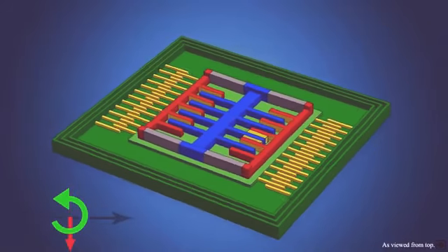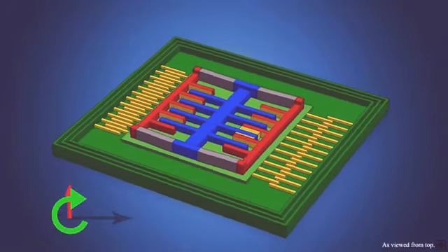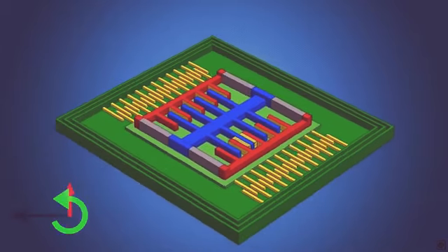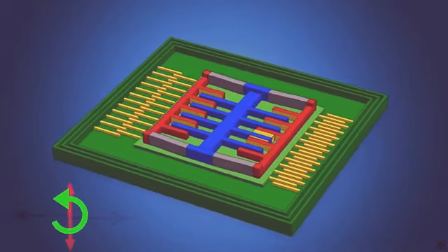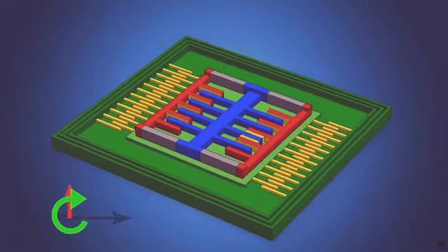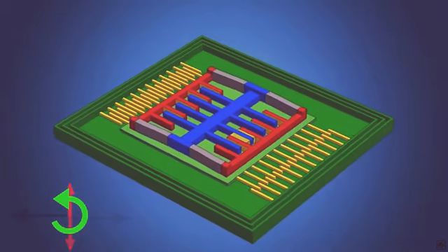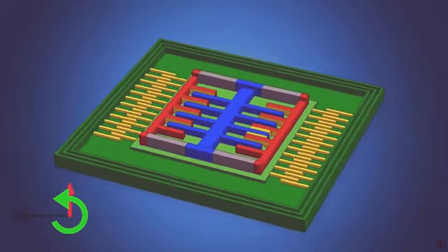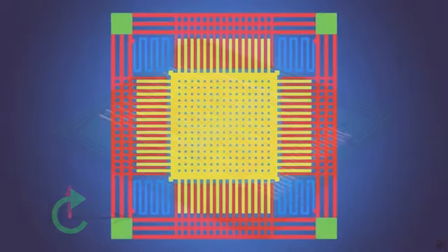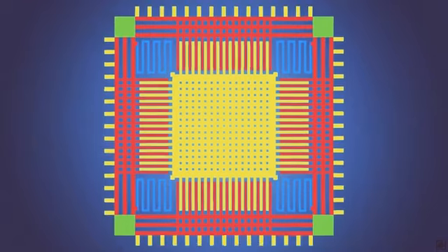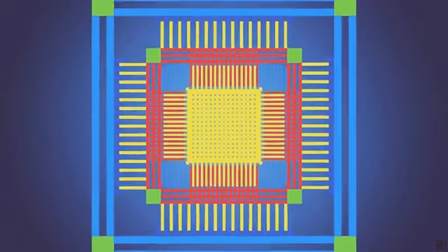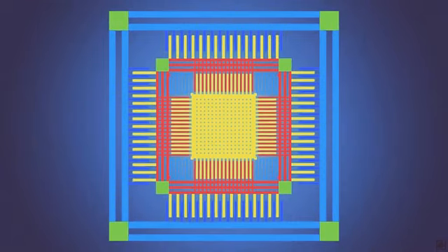This accelerometer can detect acceleration in two directions, and so can the gyroscope. Both the rotations are perpendicular to the linear motion of the accelerometer. Rotations in the axis parallel to the motion axis will not show the Coriolis effect. To scale this to the third direction, we oscillate a 3-axis accelerometer in two directions, or in a plane. Its microstructure looks like this. This can detect rotations in all three directions.